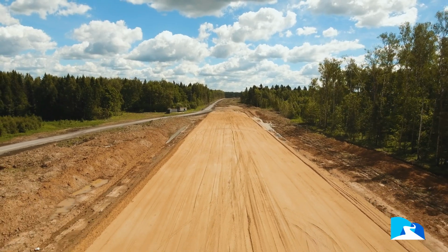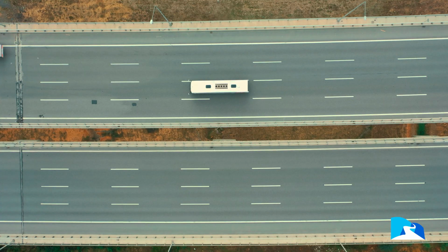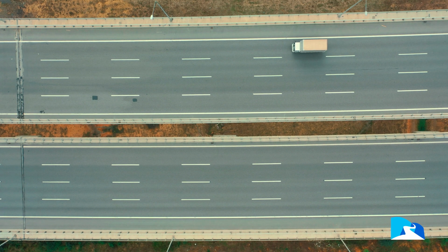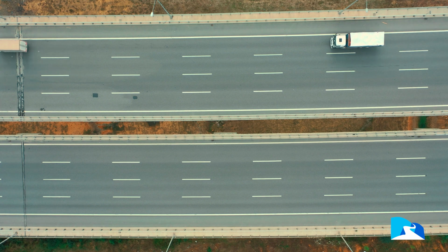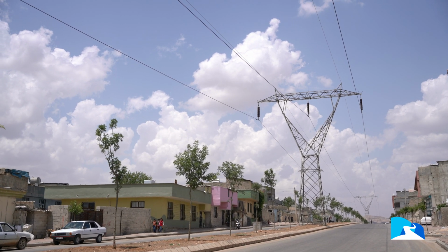Now, where does this become very important? There are situations whereby, for example, you're trying to compare an old and an existing alignment. So there's an existing alignment that was drawn, and now you have veered off. So you can compare these two alignments, both of their properties, both vertical and horizontal, and they can be shown in one drawing. Now the elements where maybe you have utilities on the side and you need to show them in the profile, that's something you can do here again with this feature. Do you have climbing lanes, auxiliary lanes, and you need to compare this? This is something amazing.